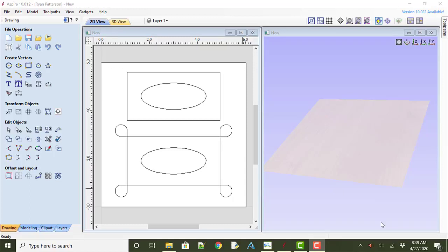In this video, we're going to take a look at using the Donic drag knife with the Vectric gadgets. We're going to do this in a couple parts. First, we're going to just quickly take a look at the gadget and create toolpaths based on the drawing that we have. We're going to then take a look at the actual video of it actually cutting. Then we'll come back in and take a little closer look at how we created what we have here.